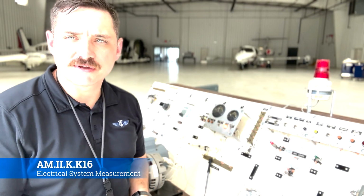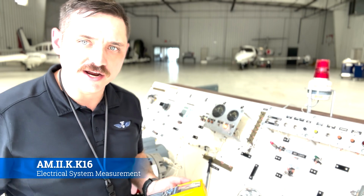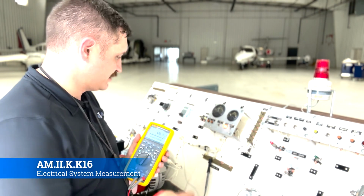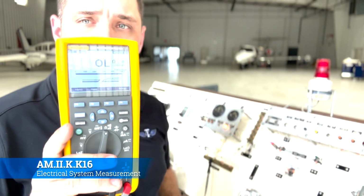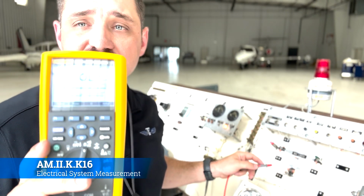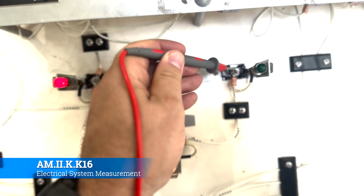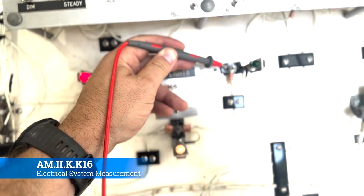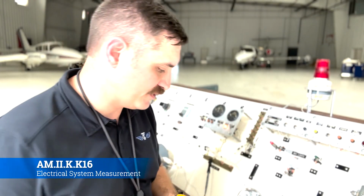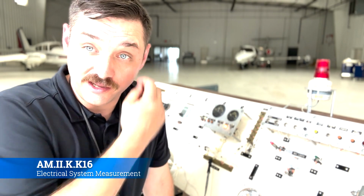Just to be thorough, let's make sure that we actually have a good continuity to ground. So we're going to leave our meter hooked up to the ground bus. We're going to watch the meter so that it's open. And then we're going to just pin to the socket, because most light bulbs, especially the incandescent ones, they ground through the socket. So we're seeing that we got 4.27 ohms through that. So that means that we have a power problem somewhere in our circuit.